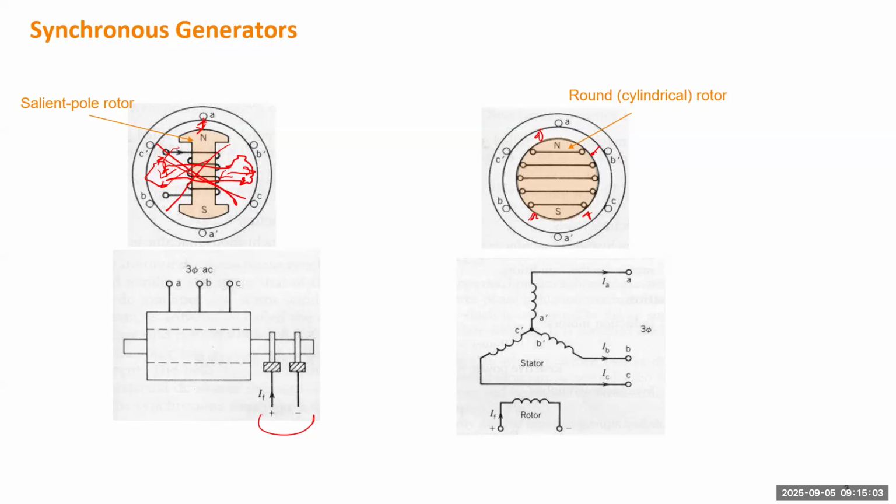If the three windings are connected in a balanced way, both spatially and temporally, which means they will have basically identical windings laid out with 120-degree displacement, you can use this Y connection to simplify the circuit. For balanced conditions, you don't have the neutral wire, so that one can be saved. It's similar to the AC circuit we talked about in the previous section.